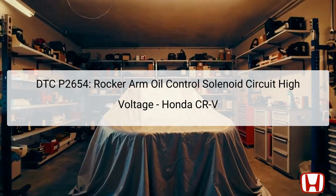The DTC P2654, identified as the rocker arm oil control solenoid circuit high voltage error, directly pertains to the Honda CR-V model from 2023 and beyond. This diagnostic trouble code indicates a malfunction in the rocker arm oil control solenoid, which plays a crucial role in regulating oil flow specifically to the rocker arm assembly.